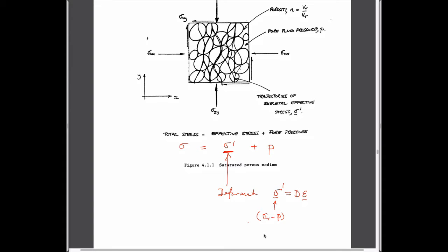These are total stresses. These are total forces that we apply. It's only in the interior that we have to define what the effective stresses are. And so in any problem that we're solving, if we only had effective stresses, then we wouldn't necessarily have to, actually would. So these are actually the boundary conditions, but the interior conditions that cause deformation are a function of these individual magnitudes of effective stresses.